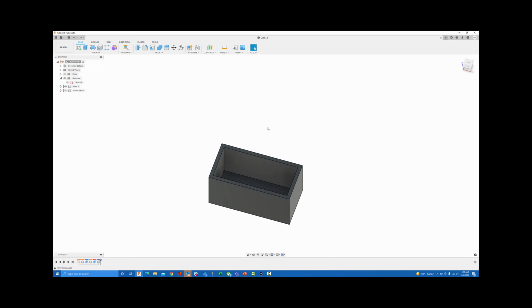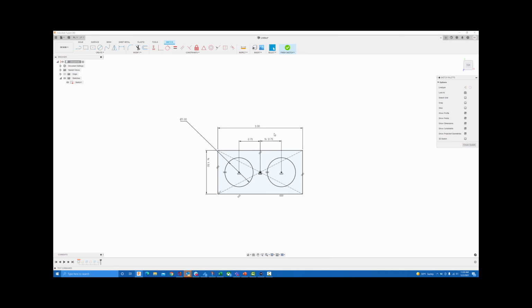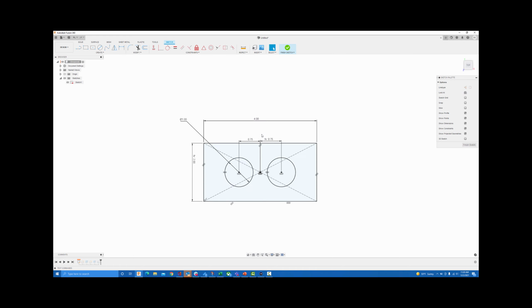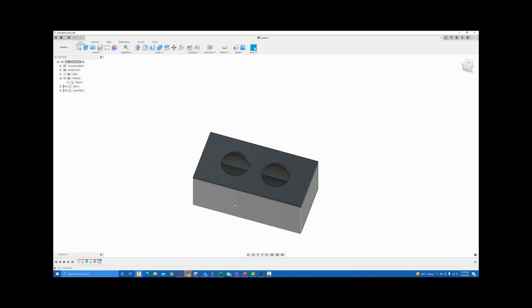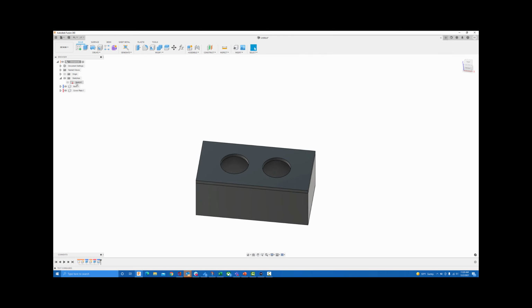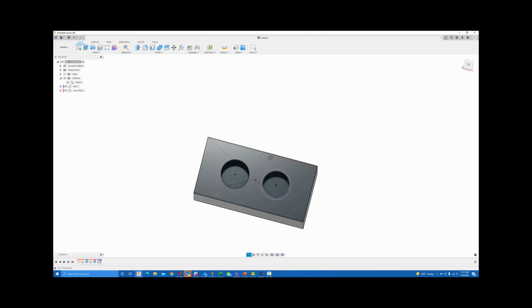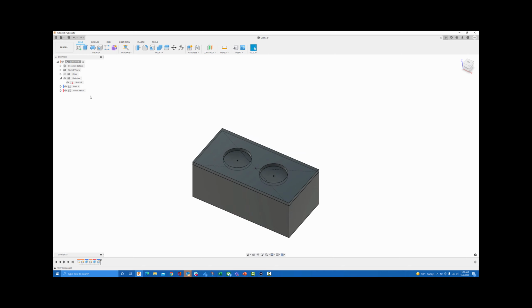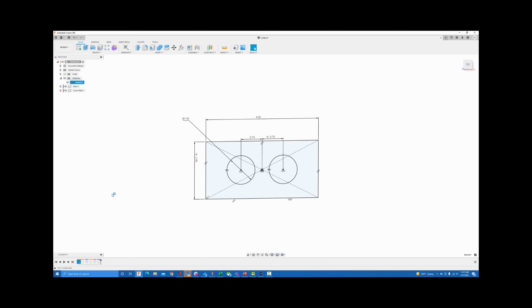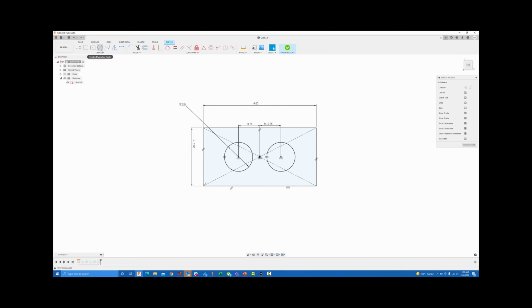Now, setting this up as what is considered a top-down design, these are all controlled by that sketch. So if I go into that sketch by double-clicking and say that's 2 inches now, or we'll say 4 inches, when I return out, you'll notice that all the top and the bottom have updated to be the same size. So oftentimes it's nice to have a single sketch that can control multiple components that will work together.